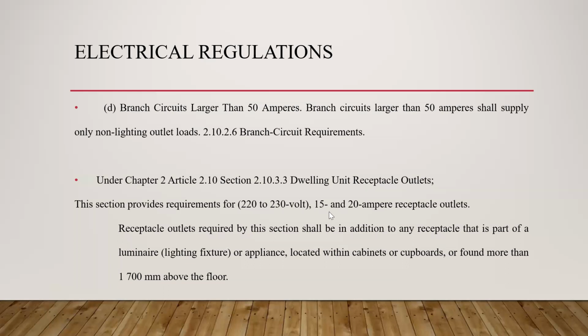Okay? So 15 and 20 ampere receptacle outlets. Yung ating receptacle outlets required by this section shall be in addition to any receptacle that is part of a luminaire or yung ating lighting fixture or appliance located within cabinets or cupboards or found more than 1,700 mm above the floor.